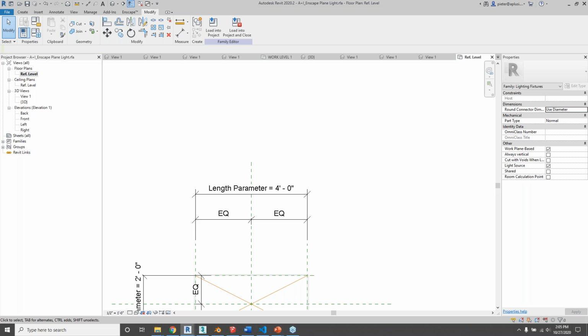Okay, great. There's a question here about creating stainless steel. Any tips for that? You need to have a good map in the glossiness. Traditionally, you would just have a color instead of a map in the diffuse or albedo slot, and then you would put a stretched noise map or something like that in the glossiness slot and potentially in the bump slot.